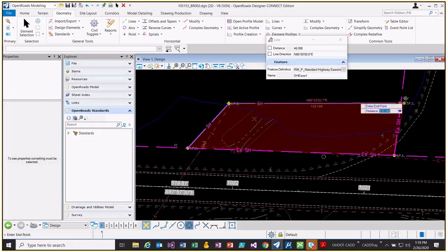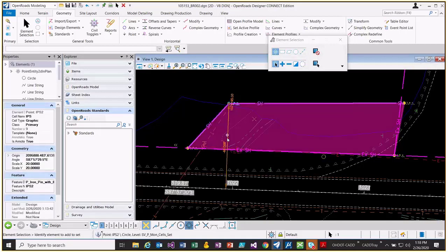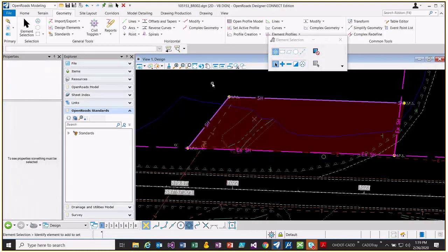So those are the lines that I would be showing in my plan work, and I would be turning off the level of that underlying parcel area. Now, since all this has been snapped to those points, if I come in and edit one of these points, maybe change this offset to -70, everything is going to move together since it's all associated with that point.